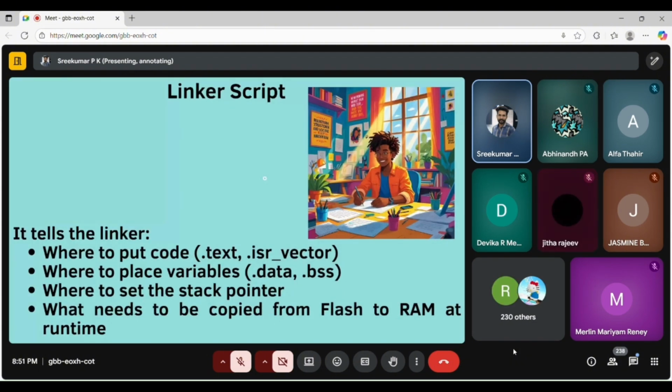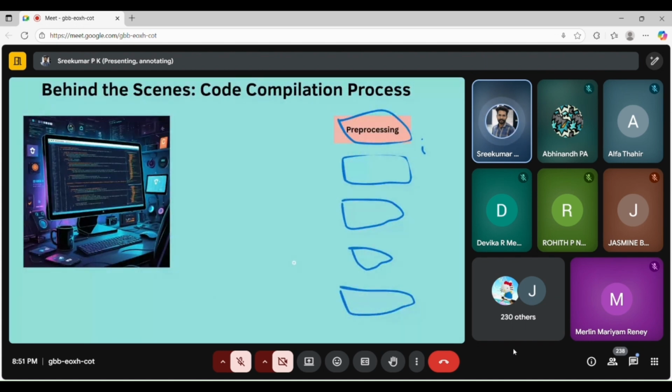The linker creates a vector table also. Inside that vector table, you can see the reset vector address. So everything is based on addresses. The microcontroller works based on fetching data, which is managed by software like the linker script, startup code, and main routine. Everything plays a role in executing the code. So these are the behind-the-scenes and tools associated with software development on microcontrollers and microprocessors.